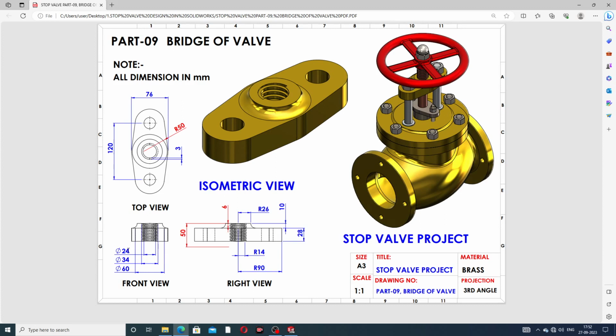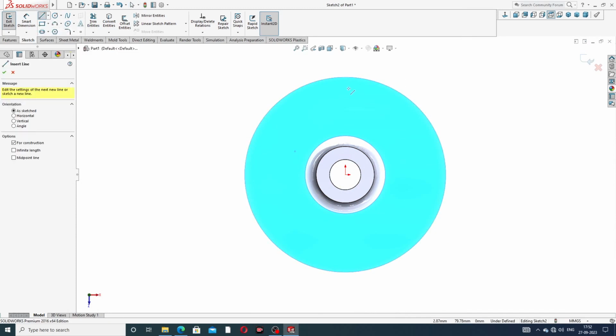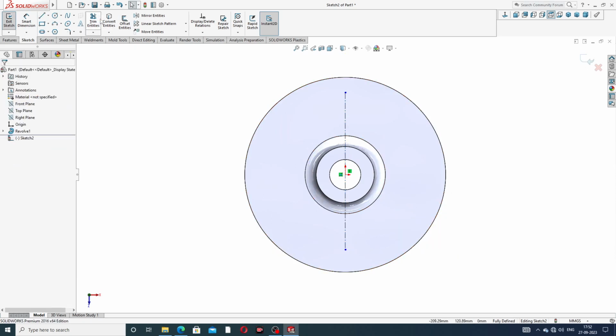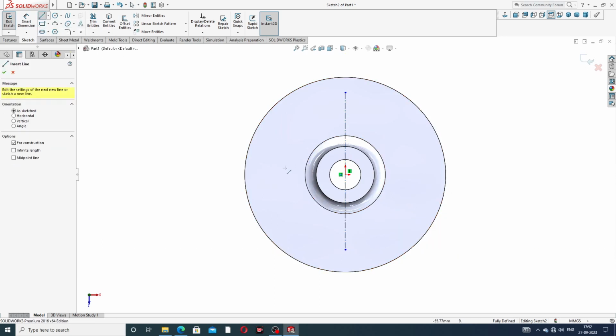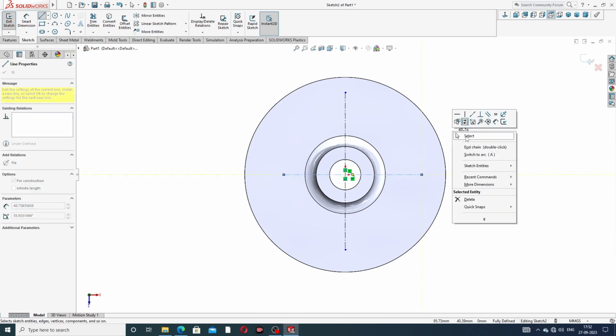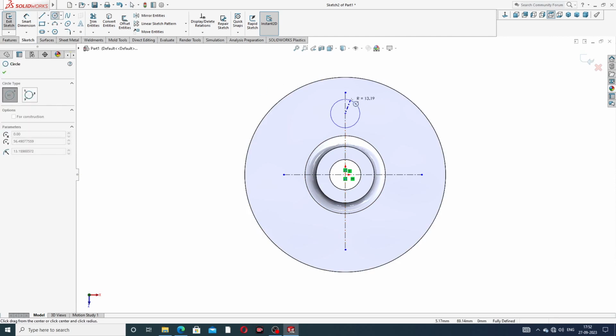millimeter diameter, and this is 24 millimeter, and this cutout is this 34 millimeter, used for a thread. Okay, and at first draw a reference line, again select both reference lines drawn here. Connect to this reference line, which is very important, and draw a circle here.